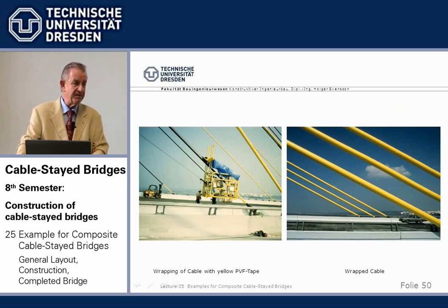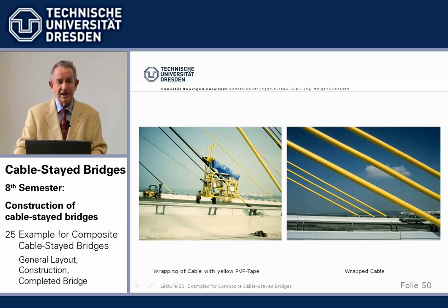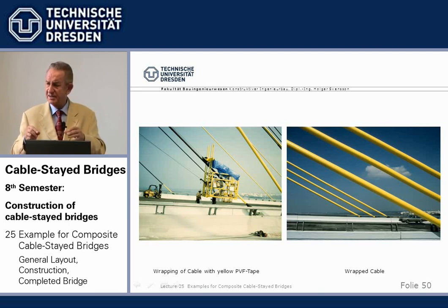Cables are in, they are cement grouted. Cement grout I showed you for the Pasco-Kennewick Bridge, how that works. And then, of course, many say black is beautiful, but sometimes with stay cables, people say, now we'd rather not have the black PE pipes, we want a color. We cannot paint because PE is chemically inert. Paint does not stick on PE, it flakes off. So the only way we found was to use tape,